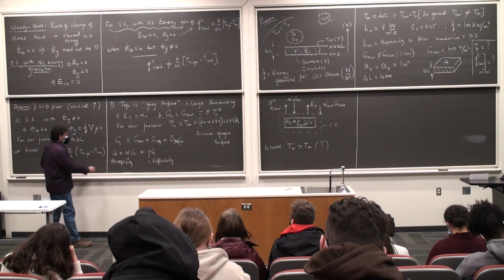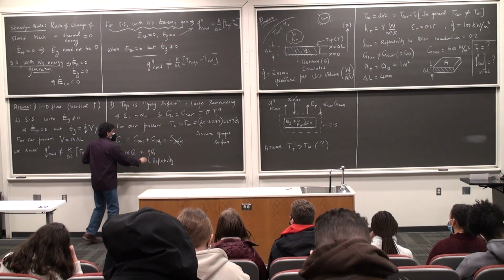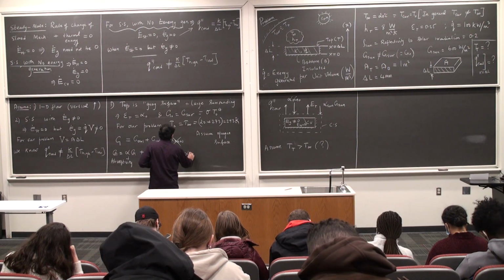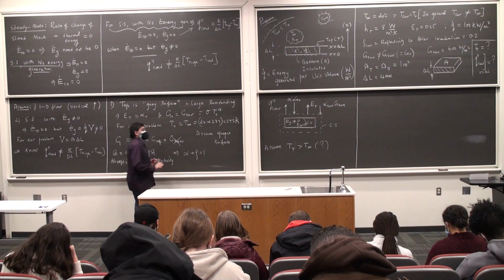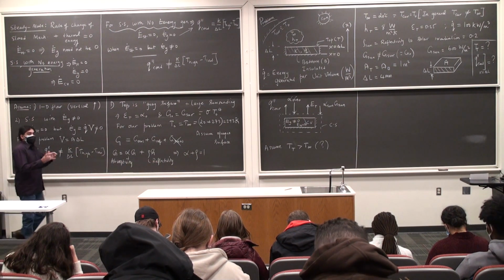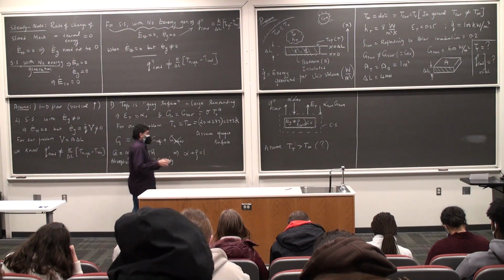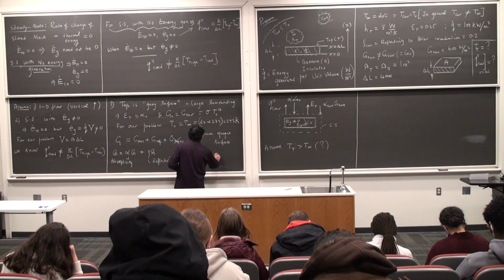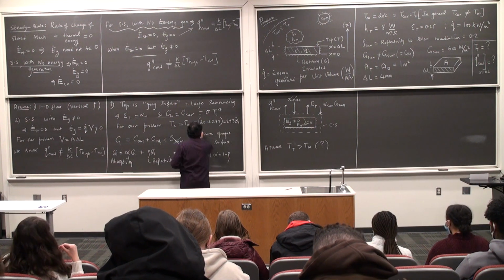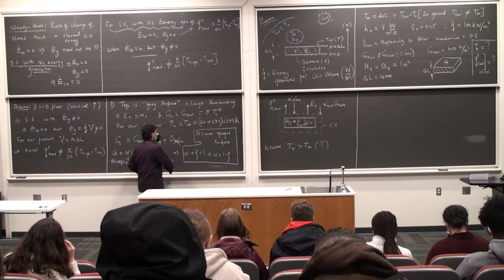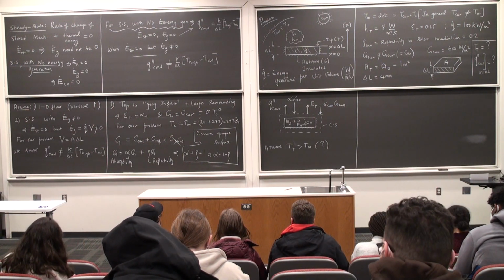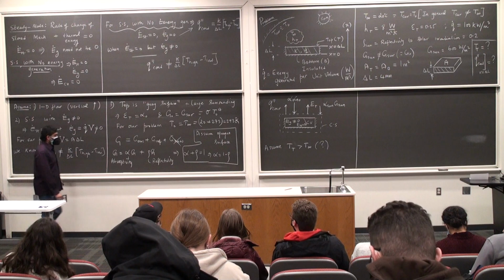It's common sense to see that I can cancel off this common term G so that I have the following equation. Alpha plus rho is equal to 1. This is true for any opaque surface. So that if I'm given 1, I can find the other. So alpha is 1 minus rho. This is for an opaque surface only. Or an opaque body, if you'd like to think of it.